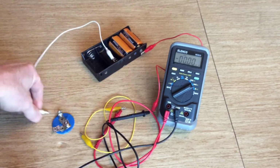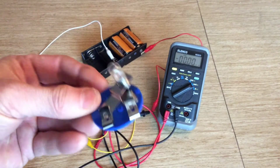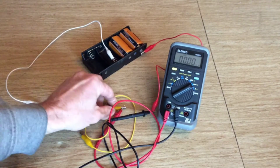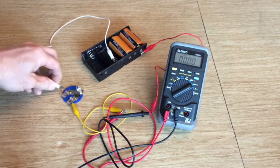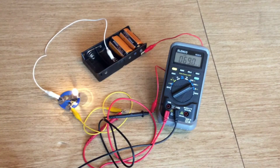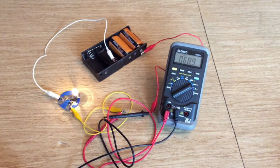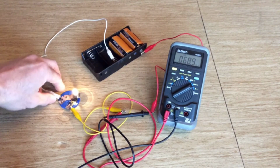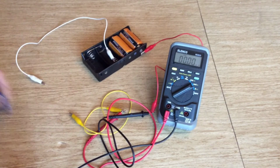Now, I'm going to take the round bulb out, and I'm going to put in the long bulb. As I put the long bulb in, I wonder what will happen to the current readings on my meter. You can see I got a little bit of brightness there, but I'm at 69 milliamps. So we went from 199 with the round bulb to 69 or so with the long bulb. Wonder what's going on there. Now guys, power is current times voltage.